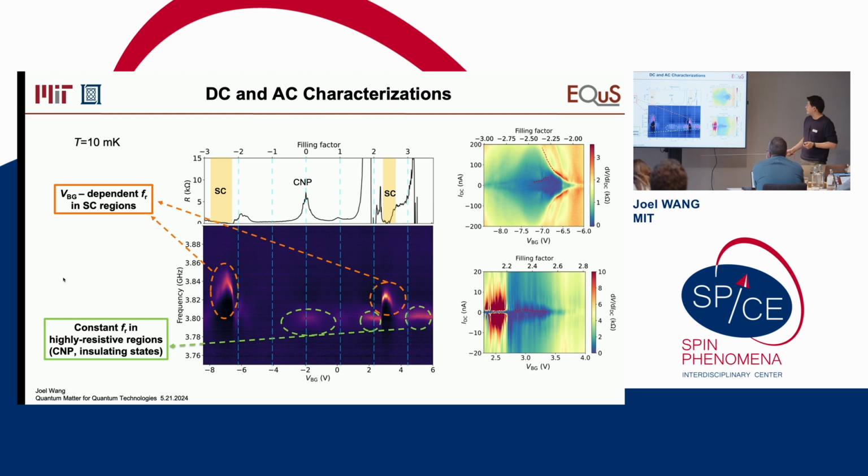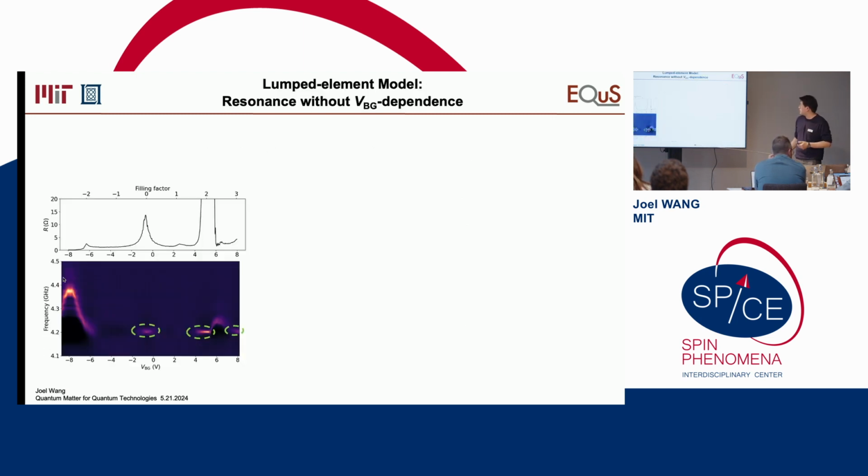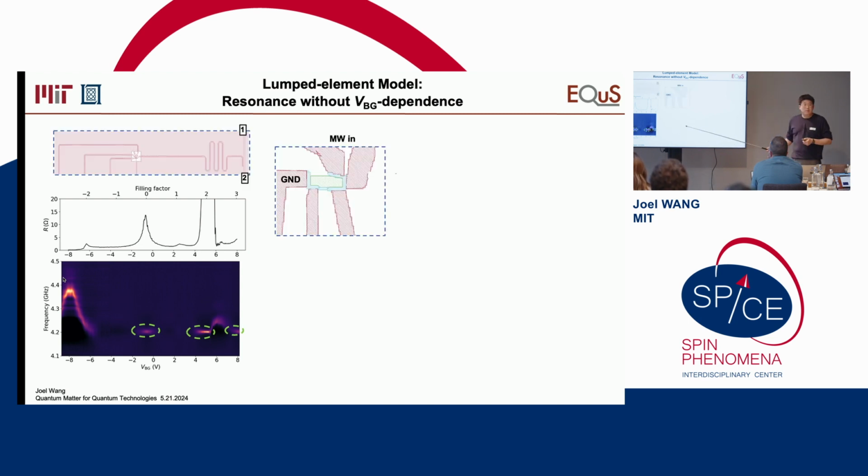So how do we understand that? These resonances don't have any gate dependence. Without going into too much detail, what I want to say is we can model this device with a very simple lumped element model, based on the device geometry and helped with microwave simulation. So what we are seeing here is the actual device, and you can understand that it considers two parts of the device when the device is insulating.